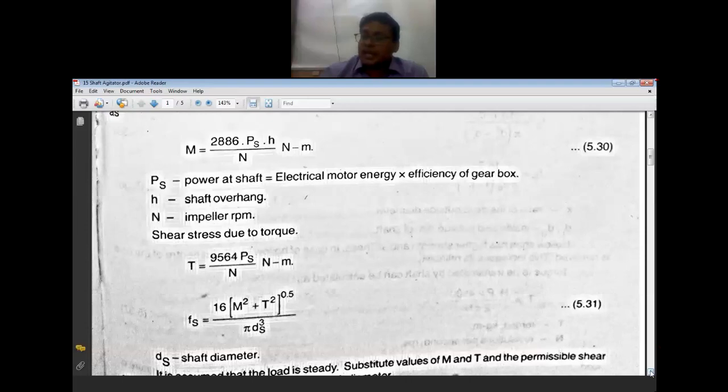Now the second situation is that of a torsion torque. Now this is a chalk. You must have cut this chalk into two pieces by applying a force in this fashion, right? You will get two pieces. Now to this same chalk I am going to apply a twisting force, a torque. Now I am going to twist this chalk. How it will cut, you have to observe. So I am going to give a twist to this. So you can see that the chalk is cut like this. It is cut into two pieces, but you can see the surface area twisting has been observed.